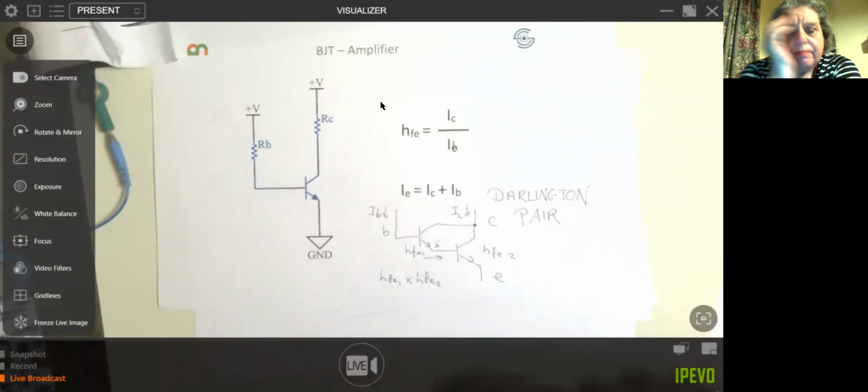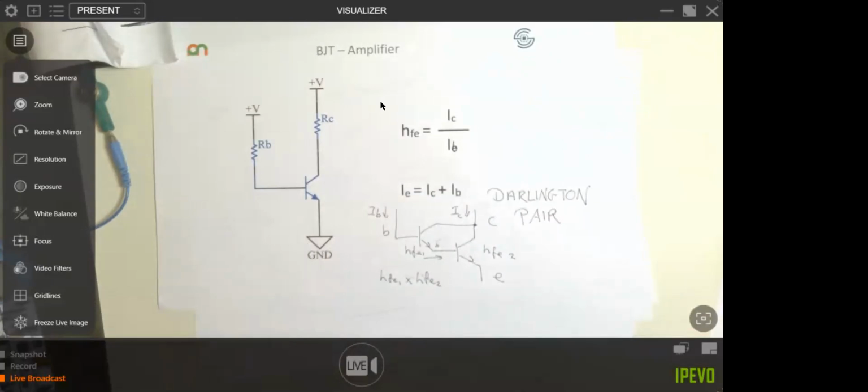Lovely. So there's so much more you can do with transistors, but we just haven't got the bandwidth to cover everything. What I have shared with you this evening are the sort of things I use them for. Certainly I use them to protect my circuits. I use them quite a lot for voltage level shifting. We saw the NOT gate. I always use them for turning motors and buzzers on and off all the time. Do I often use current gain? Very rarely in the sorts of microcontrollers that I'm designing, if I'm honest with you.